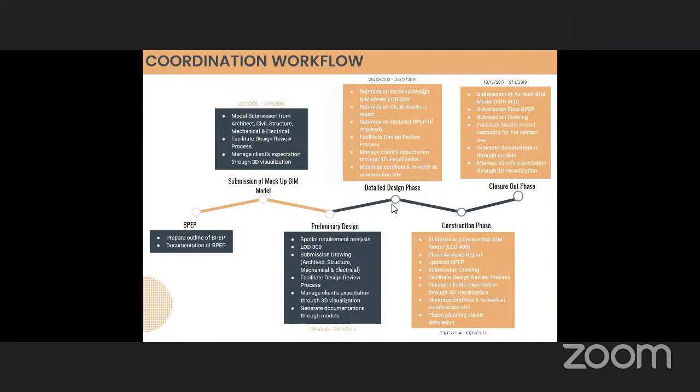And then next, which is the next phase, is the detailed design phase, which is the submission of detailed design of BIM model, which is LOD 300, and then the submission of clash analysis, and they update the BEP if required. And then for this phase, it's still facilitate design review process.